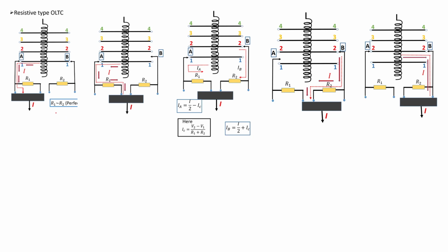So in this case, you have two resistors here, R1 and R2. So here, there is this conducting bar which is connecting these two positions here. In this case, entire current will flow through the dotted line here. So it will not flow through the resistor. It will flow like this actually directly. So through this I current is going to the line.